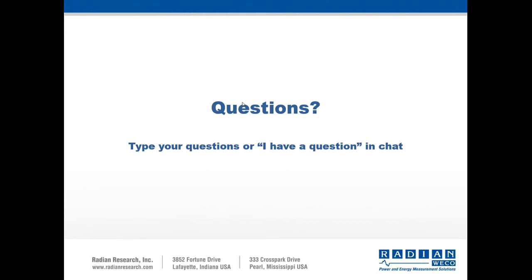There are 2 settings. One is the number of pulses, and the other one is the setting of the test duration. Okay. So when you go into test your meter, you have the option under options to test either using pulses or using a set time. So if the amount of time that it takes to test the number of pulses is longer than the test duration you have set, that won't conflict with each other, because you can either test by pulses or test by time, not both at the same time.